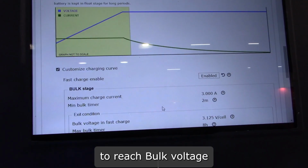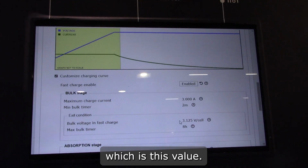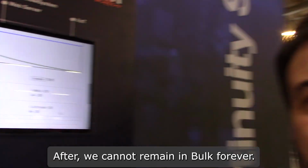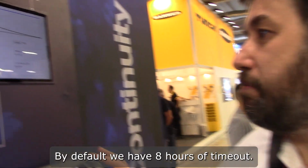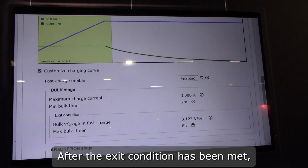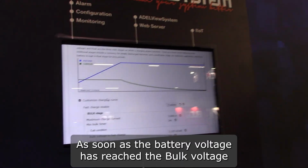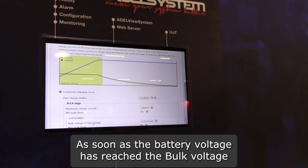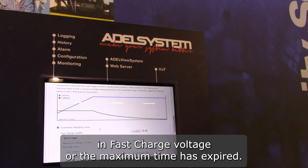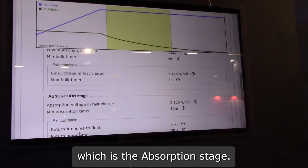The bulk voltage is stated in the exit condition, which is this value. Of course, we have a timeout. We cannot remain in bulk forever. By default, we have 8 hours of timeout. After the exit condition has been met, that is, as soon as the battery voltage has reached the bulk voltage in fast charge voltage, or the maximum bulk timer has expired, we transition to the second part of the charging profile, which is the absorption stage.